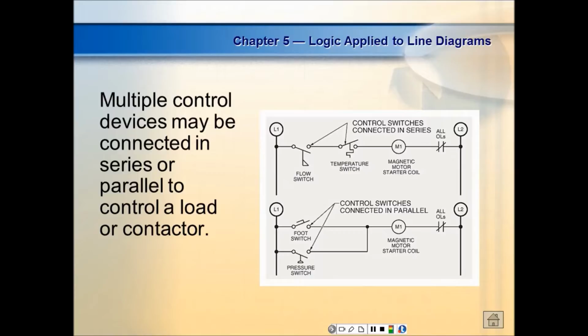It's got a little flow switch in it. If they don't sense flow of that air, the fan blowing through the combustion chamber, then they don't allow the main gas to turn on, and they won't turn on the igniter, because they don't know for sure that there's no gas in that chamber. All it's trying to do is sense whether that fan comes on or off. When it turns on, it blows a flow, and it has a little vane in there. When it blows, it pushes that little vane up, and it lets the igniter turn on.